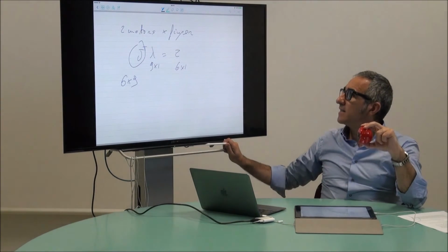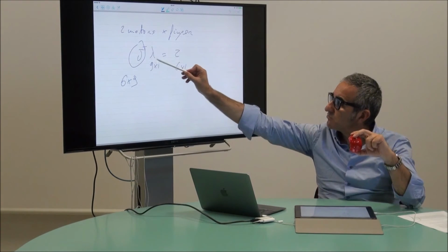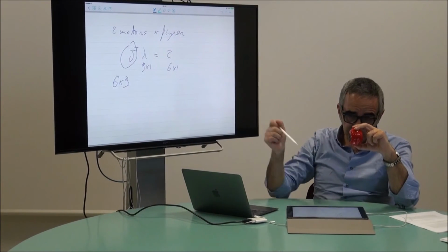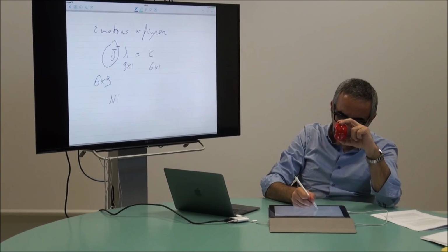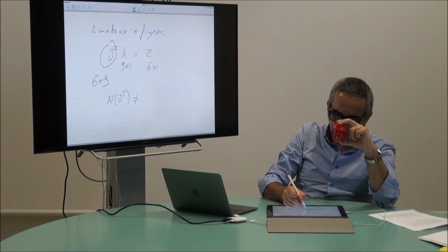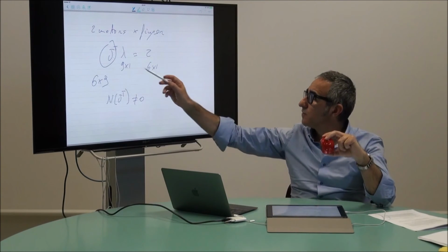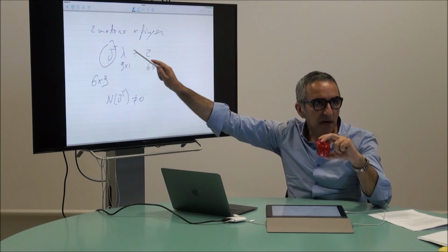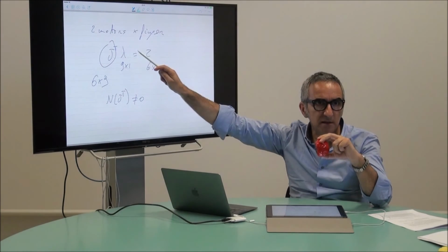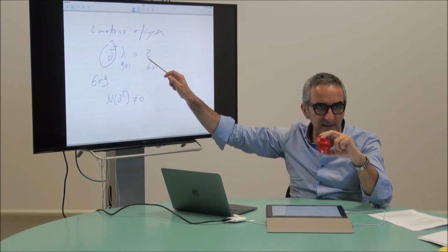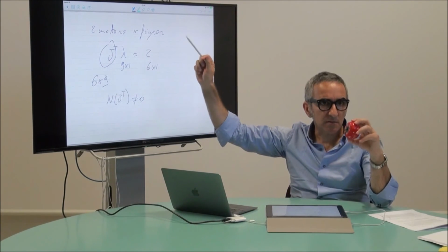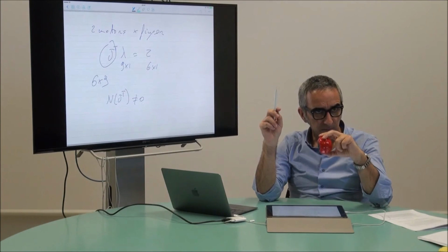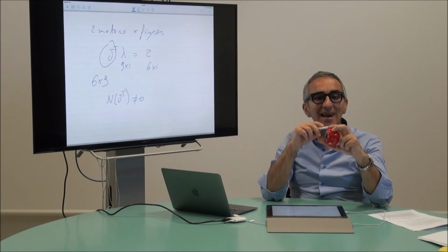Okay? Why is it not possible? You know, because now J transpose is 6 by 9 and that's for sure a kernel. In this case, for sure, the null space of J transpose is different from 0, and all the forces that go into the null space of J transpose are mapped to 0, so you have no control on that, because even if you apply a 0 torque, lambda goes wherever in the null space of J transpose, so you cannot control it. Clear?